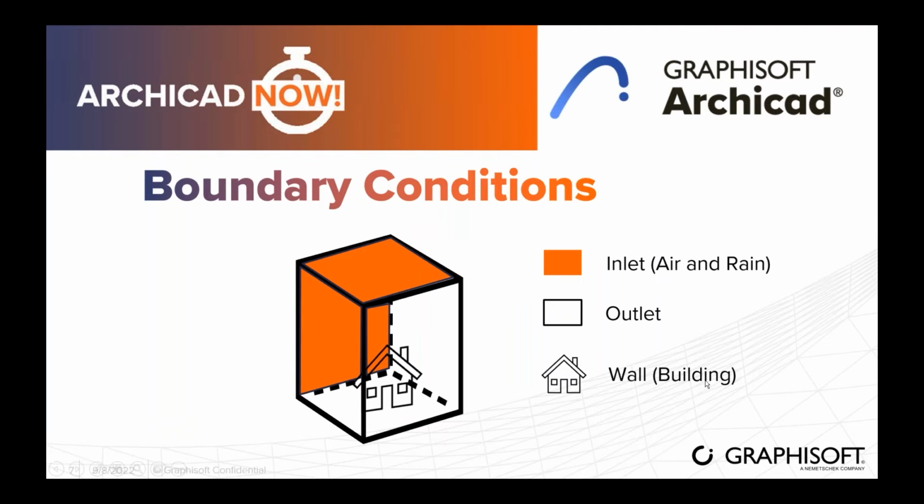So let me show a few options here before we go into the simulation in SimFlow. Here you can see I have a building, and surrounding the building I have the faces, or the mesh around the building. So I basically have to create a mesh around the building, and then I need to set the boundary conditions for those meshes.